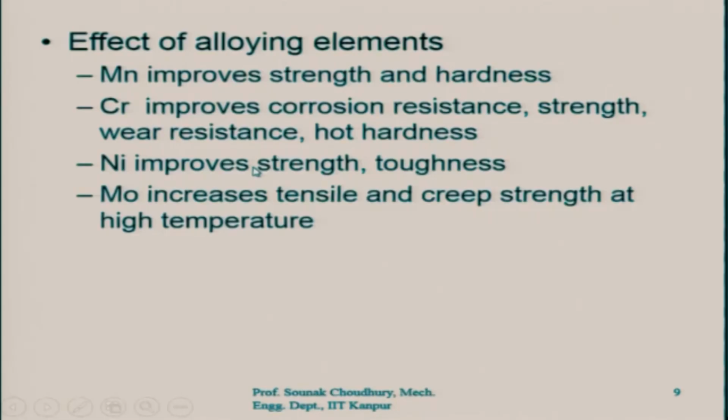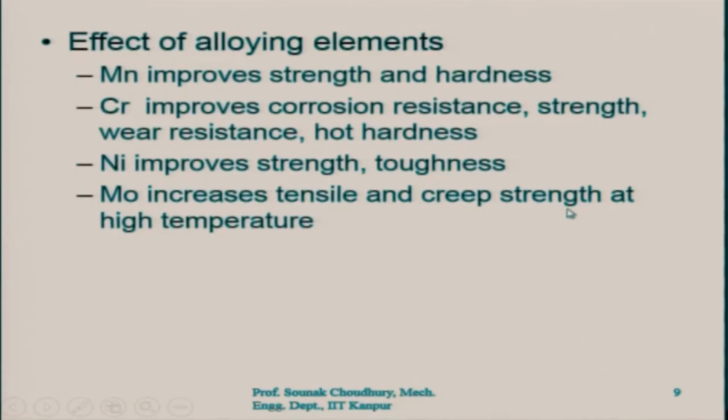Next is nickel, which improves strength and toughness, to withstand vibration or shock loads, for example. Molybdenum, for example, increases tensile and creep strength at high temperature.